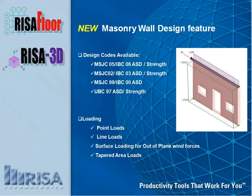We have design codes available in RISA 3D and RISA Floor. We have the MSJC 05 and 06 ASD and strength design, so the latest codes are available. But you also have some older codes available. So you have your MSJC IBC 02, IBC 03 ASD and strength, MSJC 99 IBC 00 ASD, as well as the UBC 97 ASD and strength design. So you just choose with a flip of a switch which code you'd like to be using.